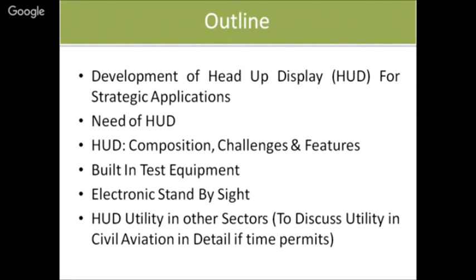So in our case, we follow certain military standards for certification and testing, and only then we go ahead with our development process. Those are called MIL standard 461, 462. There are environmental standards, 8110. So we follow all those, and then only we can have something which is airworthy. Airworthy means which can fly or which can go into the aircraft.